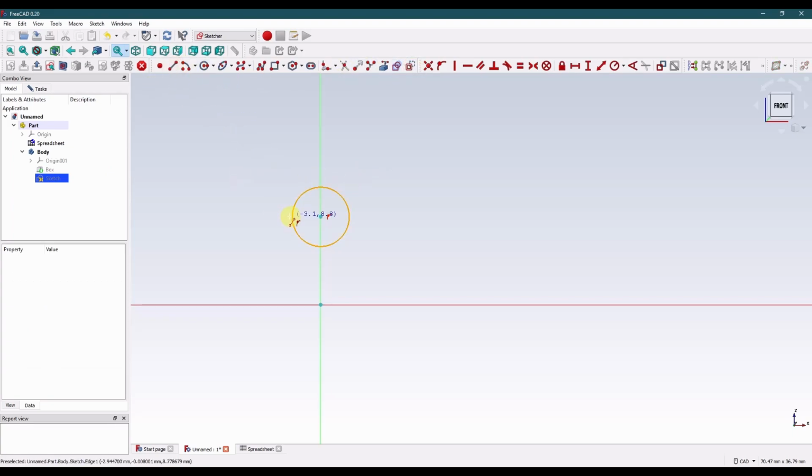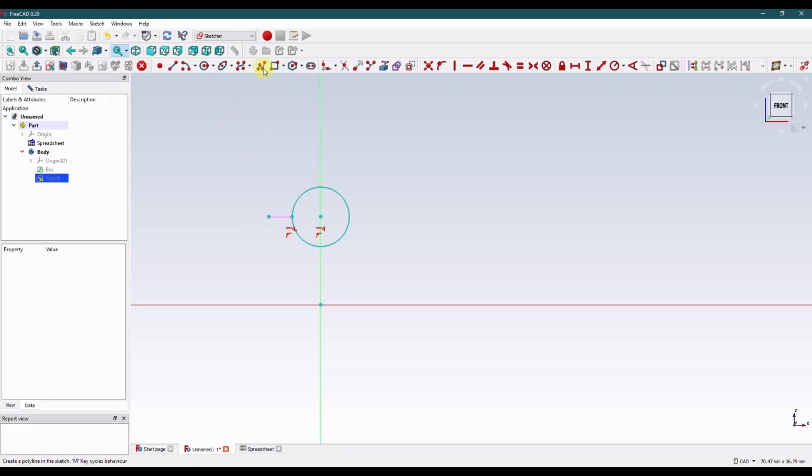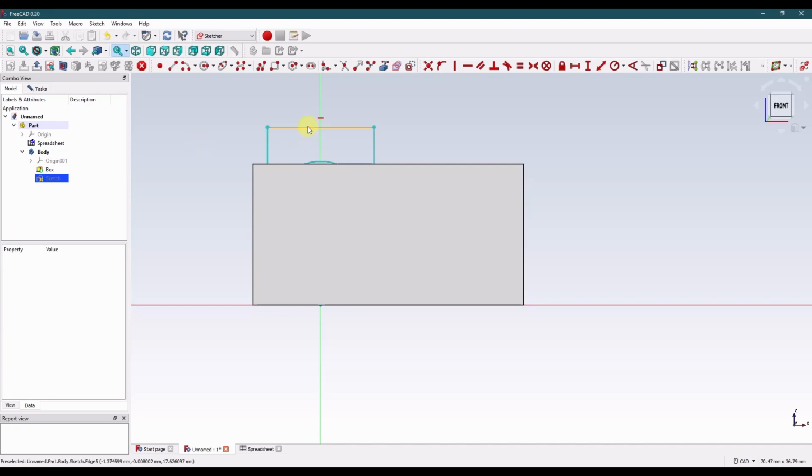I'm going to create a reference line over here, make that horizontal, and horizontal to there. Let's make an outer arc coincident to that. Then take a line up here, over here, and down. And I'm just going to make these horizontal. So that's locked in place. Now referencing the body, we want to have this over here because this will be our cut.